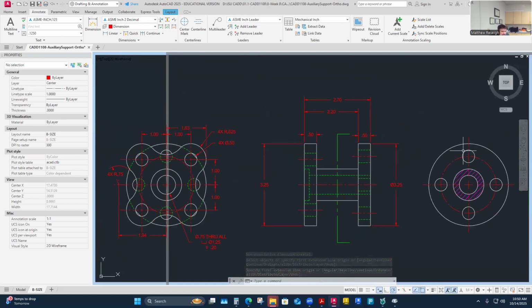And it's the size of this that I'm thinking about. There's size, diameter, and kind of the depth here for the size of this. And maybe in some future, in the combination of these dimensions, some become clearly referenced and others stay as critical. So, are we saying that we're establishing a new control here? Well, not necessarily. It could be that this is the control from the same datum, so that the point 0.5, 2.2 and 2.7 are all pulling from this control. Maybe this one's reference information at that point. We don't know, but I'll leave all four of those there.